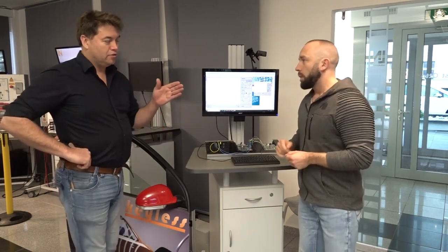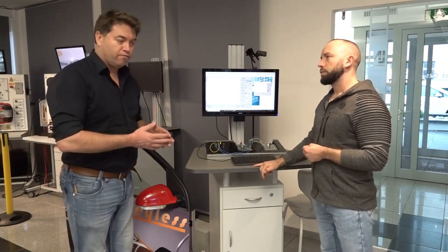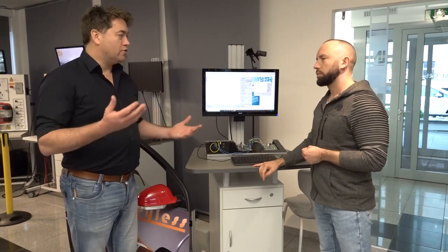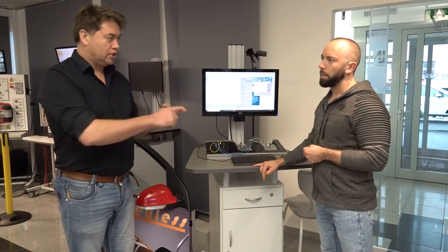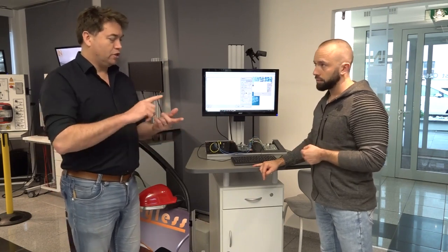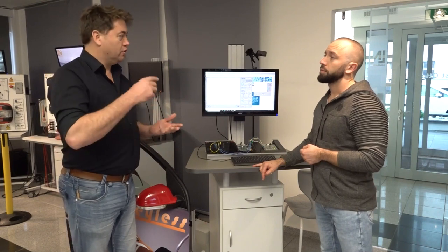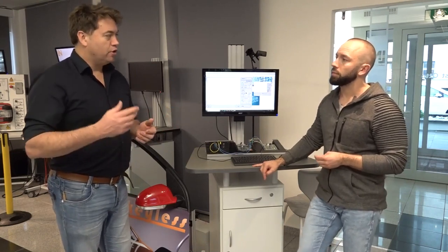If you think about the different speeds, we know this from computing: the faster computers are, the more they cost. That's the reason why we might have different CAN bus speeds on the vehicle. For sure. CAN high speed is used for safety and motor control: your braking systems, your steering, your sensors, your airbags. Exactly, they're using CAN high speed. If it's something like turning the windows up and down, then that would be a low speed CAN bus.